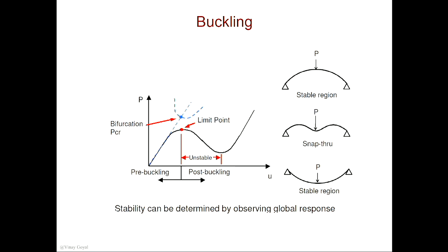So in that case, that's clearly unstable because with reducing load, the deflections are becoming unbounded. They're becoming large. And so that's buckling that's unstable. But once I reach this point here, you can see that both load and deflections increase in a stable way. So for example, I have this configuration. I can keep increasing the deflection here and the load, and it won't go unstable anymore. It's basically in a stable state at that point. A lot of our structures are under load control, so when you apply a load, the structure will go unstable in a lot of our cases.